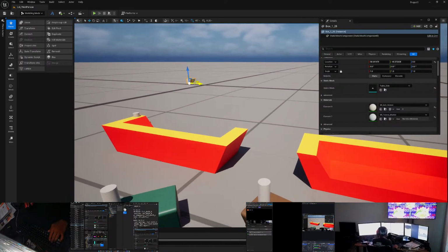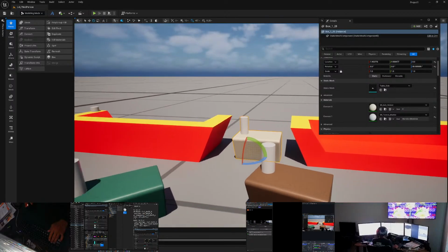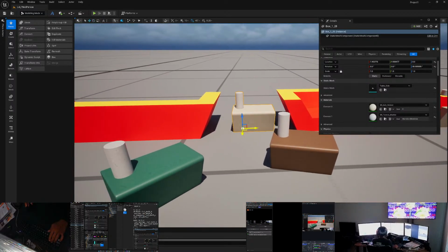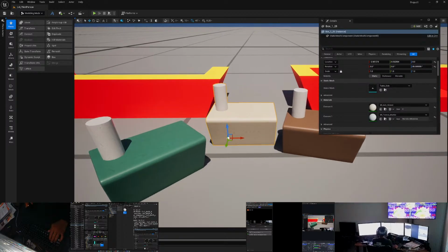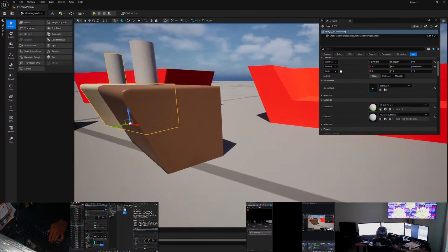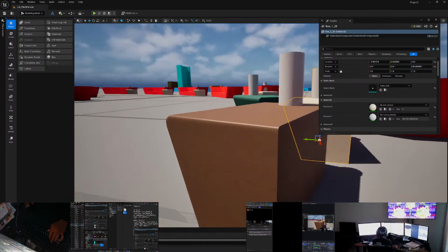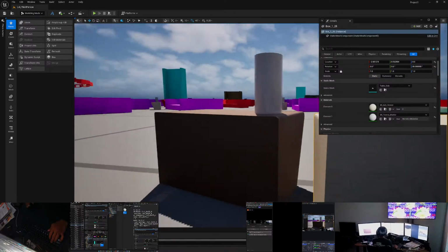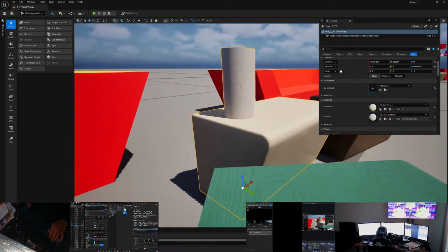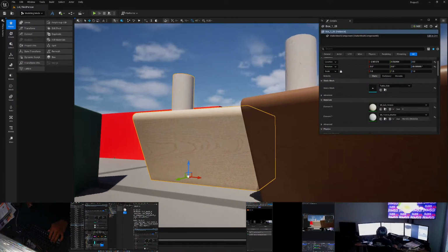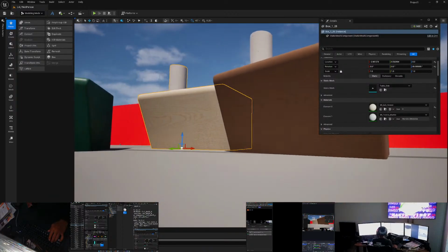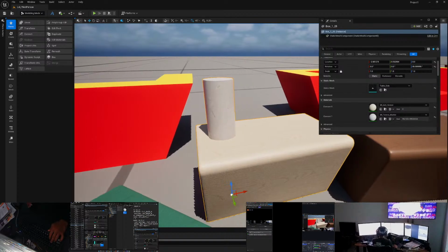So these are just some quick easy tools. I don't have bevel tools inside of SketchUp that I'm comfortable using because it's going to break my SketchUp model, but you can go into Unreal Engine and create those bevels directly with the modeling tools, and then project UV with the PBR material applied.